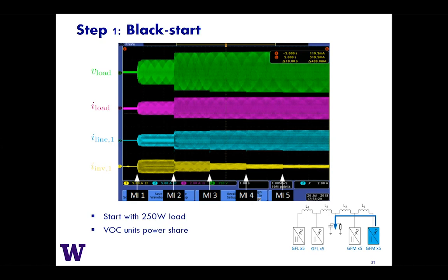So the only part we neglect is the switching, which, based on the way the controllers that we're using, or most controllers I think are using, average mode control. So averaging out the switching anyway seems like a suitable way to move ahead and get something workable. But it is nonlinear, which is why I skipped the algebra, because it's just a bunch of nonlinear algebra that no one wants to look at. But yeah, it's there. No, there's no saturation on that.